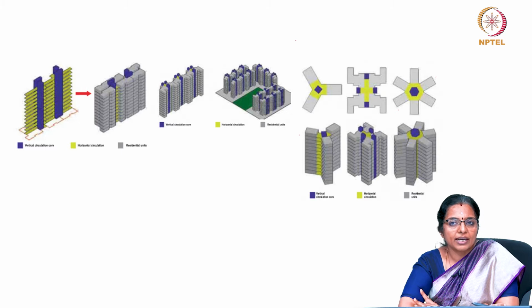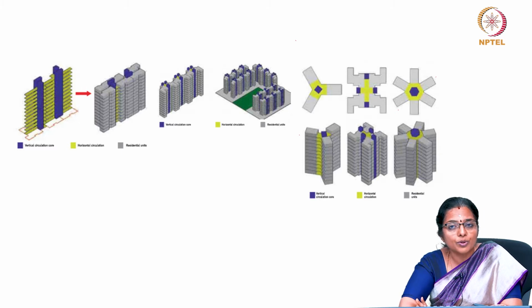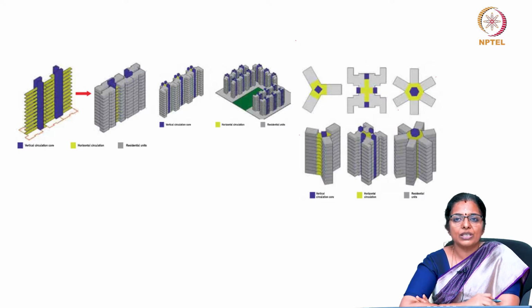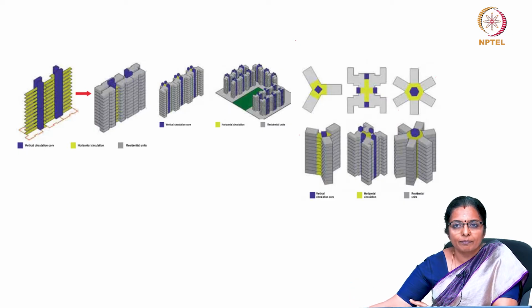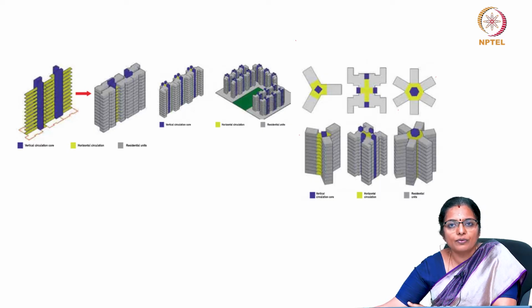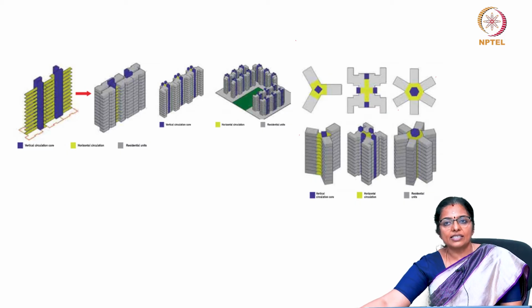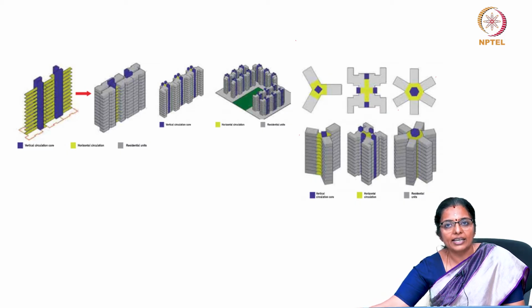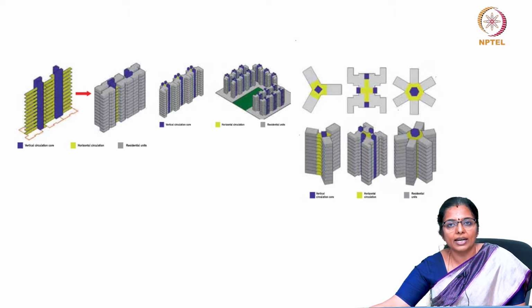Building blocks should be arranged so as to benefit from mutual shading, to minimize solar exposure on the vertical surfaces during summer months, and we should look at mutual shading in greater detail. And we must also consider the height of the context buildings, the distance between the buildings, the latitude and its location. So, the main objectives in terms of form and orientation in hot dry climate are